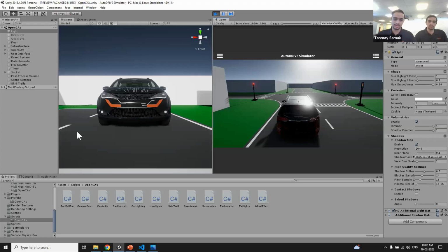So this is just a script. We can change the fidelity of the script. We can have multiple scripts which are switched when you change the dynamics quality. So you can have as crude a simulation as one that is basically just directly commanding wheel torques without considering any driveline properties or any other vehicle dynamics properties. Or you can have really detailed dynamics models which are even more detailed than what we just showed in today's demonstration. And similarly, we can do that for collision meshes as well.